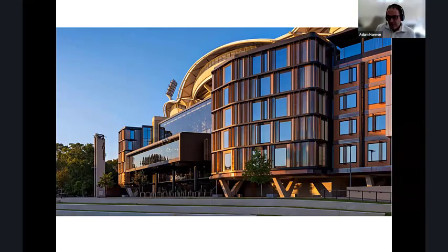Sure. Look, I think technically the minimum building life for this sort of project would be 50 years, but that's really a minimum. All of the stages in this would be envisioned to be a lot longer lasting in that regard. Hotels do from time to time do interior refurbishments, and we can imagine that one day they may wish to do a new concept for the lobby. They may wish to do another restaurant concept internally, but the structure and the facade should be anywhere between 50 up to 100-year lifespan.